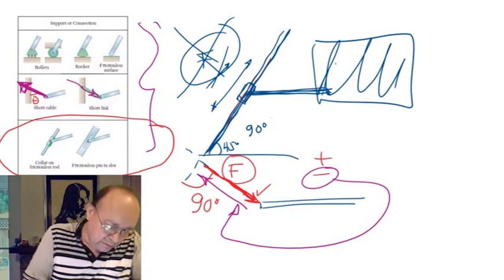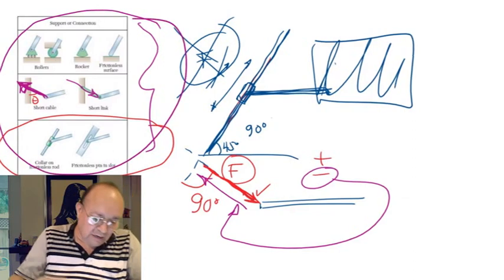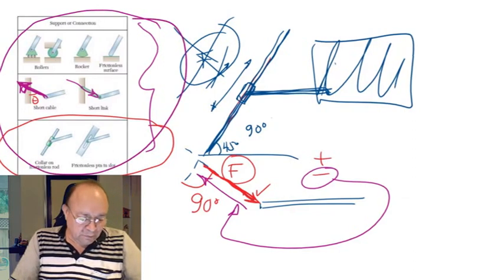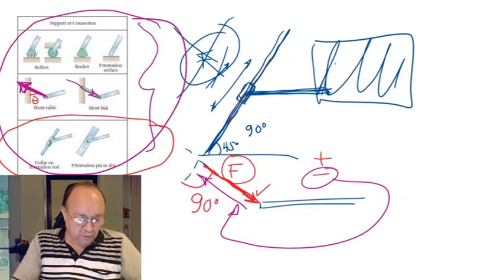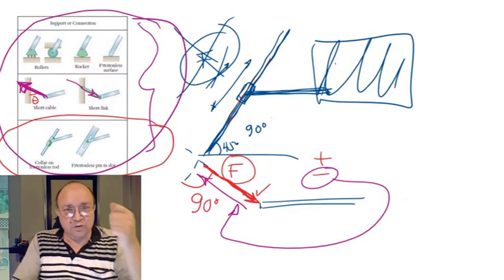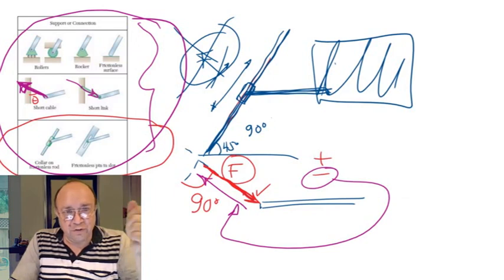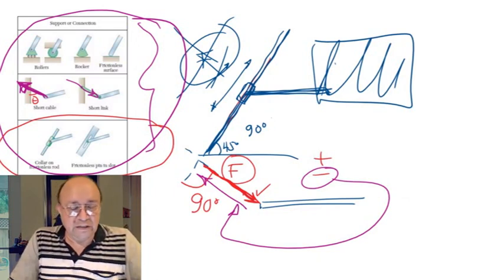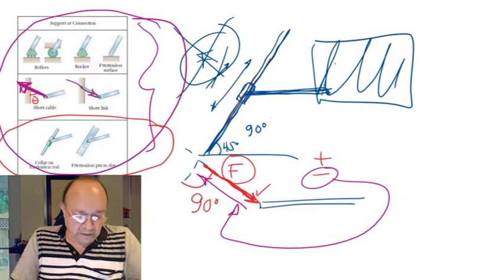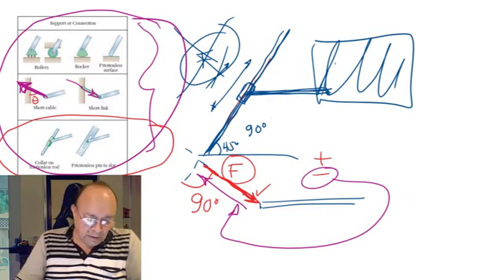So all these supports have known direction. The unknown is just one unknown, the magnitude of the force, right? You assume the sense of the force in any sense that you want, and the sign of the result will tell you if your assumption was correct or incorrect. If it was incorrect, well, you put it in the right sense for the results. Now let's see the